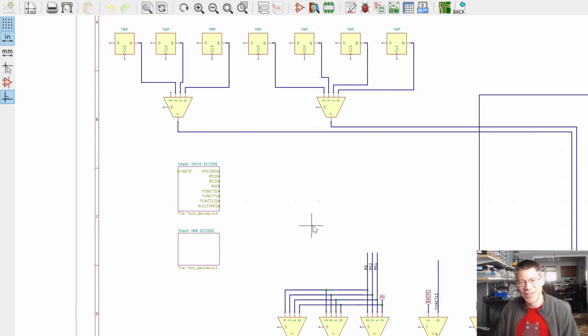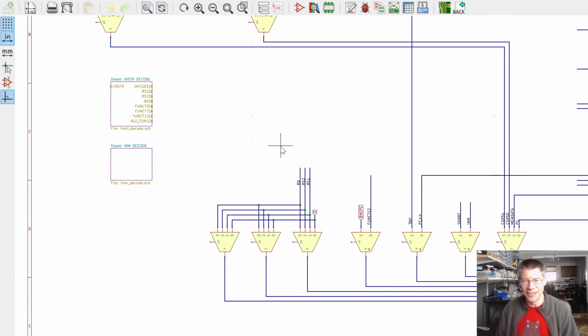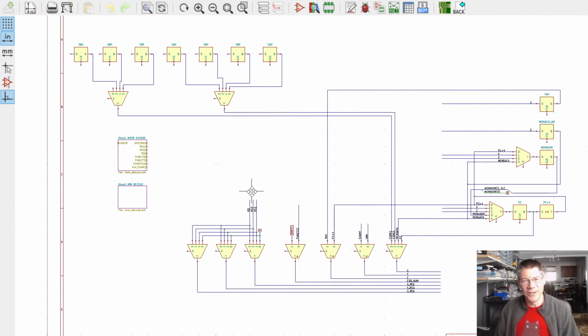Probably the most canonical project to do with a GAL is to make a 4-bit binary to 7-segment decoder. That way you can display the digits 0 through 9 and A through F with a GAL. The thing about GALs is that there are some packages on GitHub. One is written in C, one is written in Rust to actually generate the bit streams. You still need a programmer.